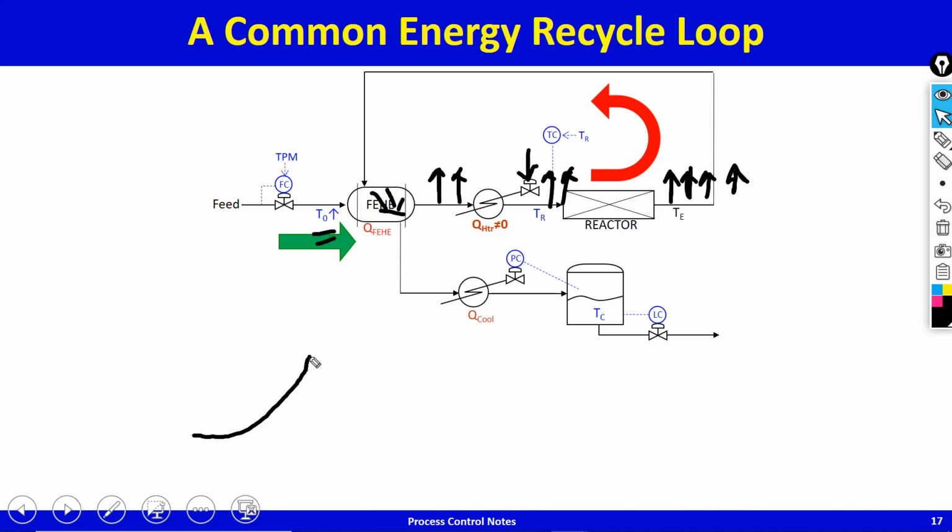And the thing that this reveals about the process is, for variability of the energy input, enthalpy input into the recycle loop, with this scheme of operating things, the temperatures inside the recycle loop keep increasing.